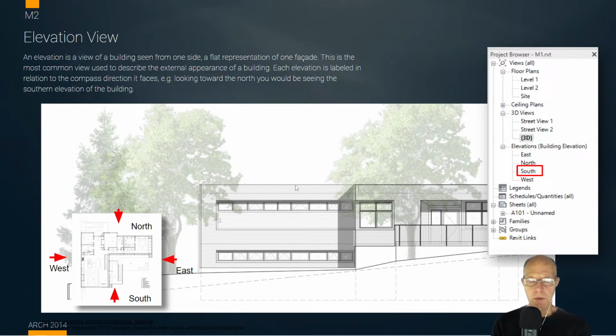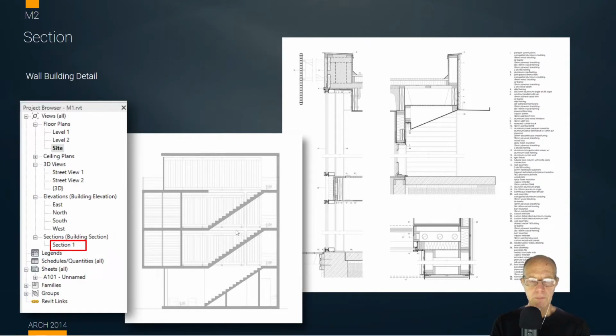Pay particular attention to this elevation. It's really a very attractive one. It is a very simple one. The trees are ghosted out. There's nice line weight. You get an idea of the change in the topography, the level of the soil that goes around the building. We get a little shadow under the windows to indicate that they might be recessed. There's a little of what we would call poche, or an effect of the materials that the building is constructed of.